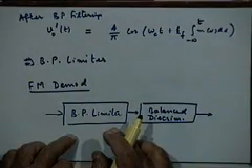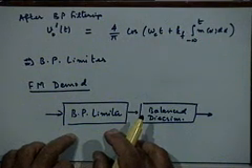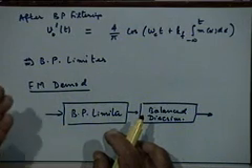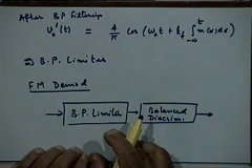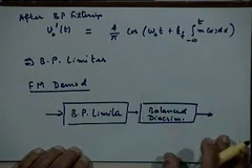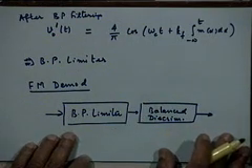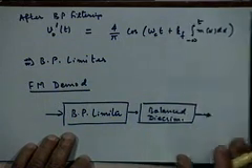And of course, this is a required and necessary component for a proper FM demodulation, right, particularly in the presence of channel imperfections. If the channel is perfect, we do not need this, right. If the channel causes no amplitude distortion, no envelope variations of the input signal, we do not need a band pass limiter, but invariably the channel will impose some distortions, will include some noise, and therefore there will be some amplitude variations, and therefore we need to have a band pass limiter, right.